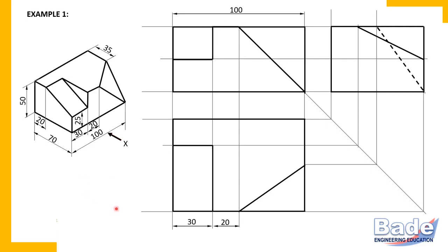Okay. Now focus on width dimension or height dimensions. Okay. 25 height. So I measured 25 height and 50. Here I told you this is chain dimensioning or dimensions in series. Here dimensions are parallel dimensioning. When you insert dimensions, lines or dimensions parallel to each other, remember smaller dimensions must be closer to the boundary of the view.